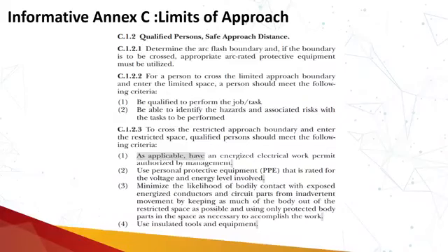So as applicable, have an energized electric work permit authorized by the management. If it's some repair, replace, or any other task, you should have an energized electric work permit. Use protective equipment that is rated for the voltage and the energy level involved. So if he is working within the restricted approach boundary and the arc flash boundary is greater than the restricted approach boundary, he will be wearing personal protective equipment.